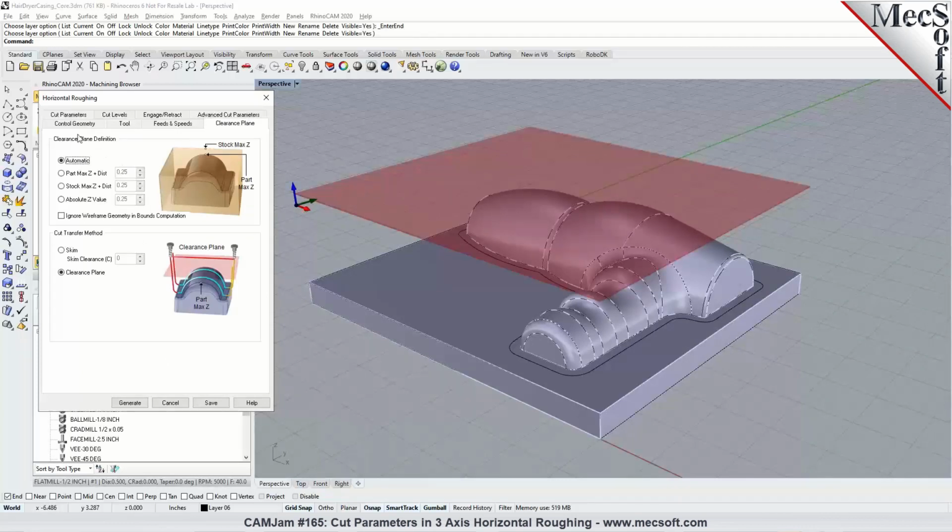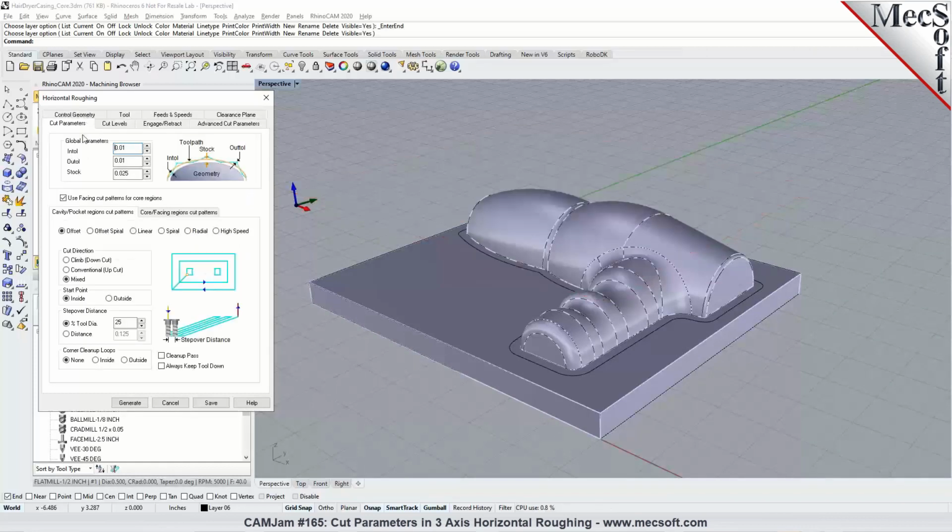It's set to automatic, so we are working over from left to right as we work through each of these tabs in the roughing operation. Under cutting parameters, we specify the tolerances, the stock allowance. By default, the roughing operation leaves 0.025 stock. So you want to then go back and do a pre-finishing and a finishing operation to remove the stock. You can change these parameters and values.